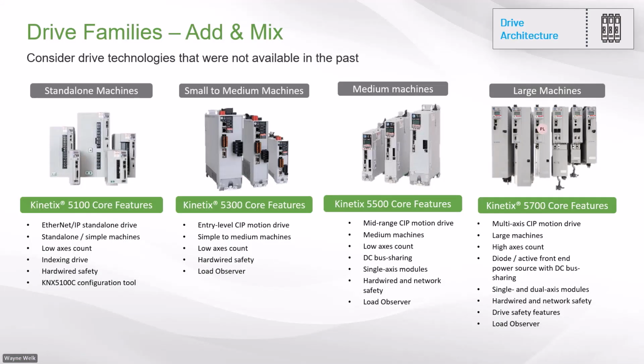So while Rockwell offered servo drives using other communication protocols in the past, the current product lineup for Rockwell Kinetix Motion has been narrowed to focus only on EtherNet/IP servo drives. Kinetix 5300, 5500, and 5700 all utilize what's called the CIP Motion protocol from ODVA that delivers high-performance deterministic motion control required for closed-loop drive operation using standard unmodified Ethernet.